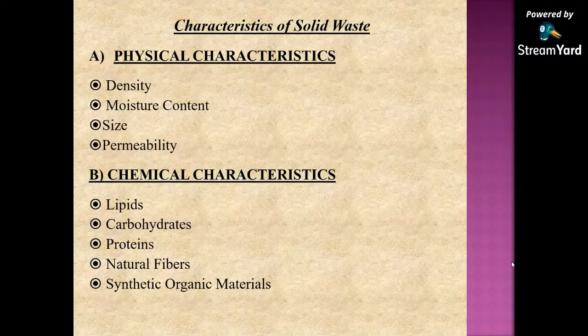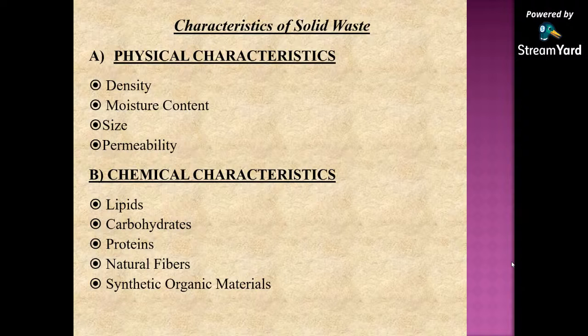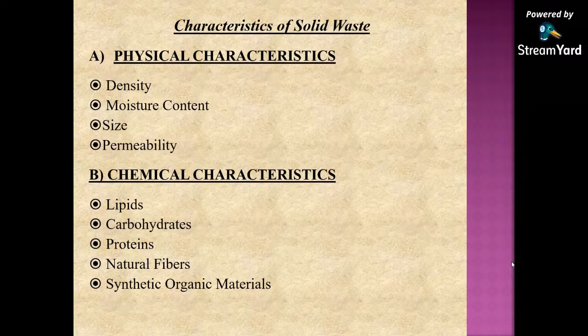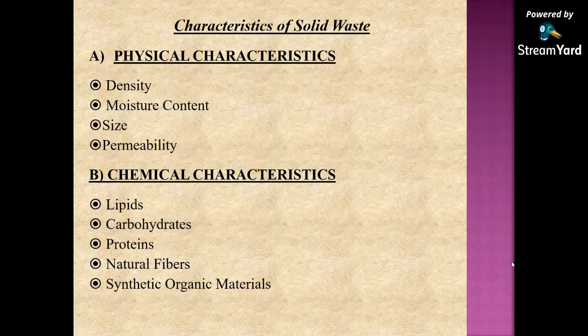Nowadays, much attention is given to reducing this component at disposal sites. Plastics have a high heating value, about 32,000 kilojoules per kilogram, which makes them very suitable for incineration. However, among the plastics, polyvinyl chloride, that is PVC, when burnt, produces dioxin and acid gas.